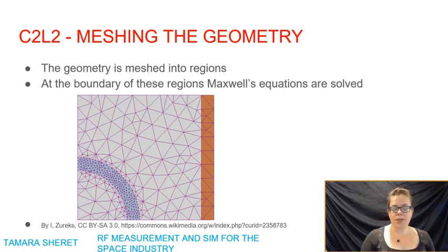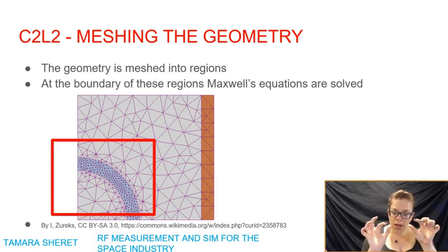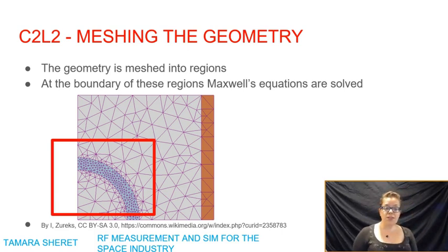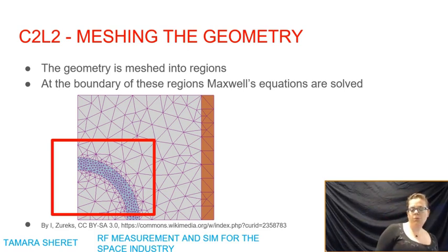What you're going to see is there's a difference. You get a differential meshing. In the kind of sparser areas where there's nothing of interest, the mesh is quite large. Whereas the mesh adapts if you've got intricate areas and it meshes into smaller tetrahedra, so you get a more accurate result. The good thing about HFSS is it can actually simulate inside the thickness of the grid line, which was actually really important for getting the reflector to work correctly.